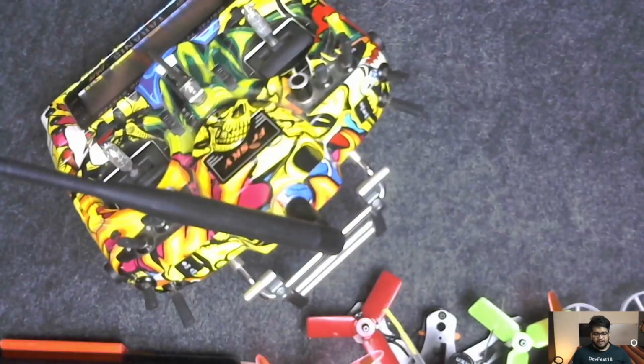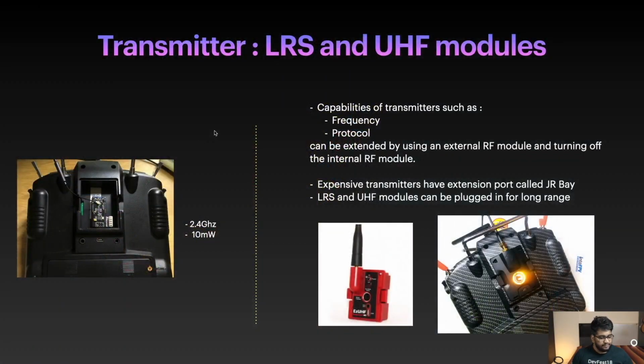So what you are doing here is basically increasing the capability of a transmitter. You are changing the frequency because this module runs on a different frequency. If I remember correctly, it works on 900 megahertz, and it can change power level up to 1 watt. So you can increase the power level if you already have permission to do that, and if you have programmed the module correctly.